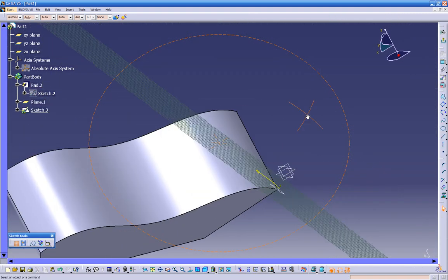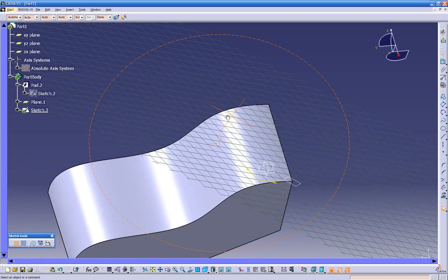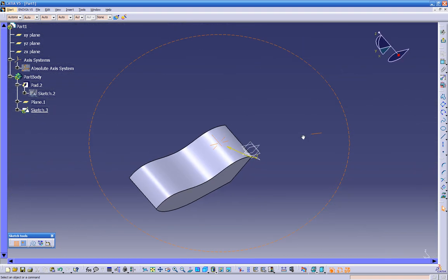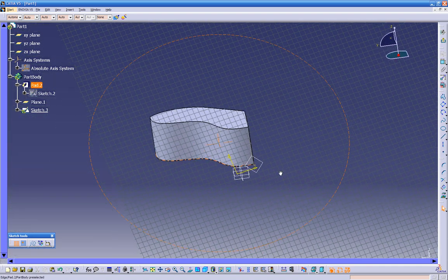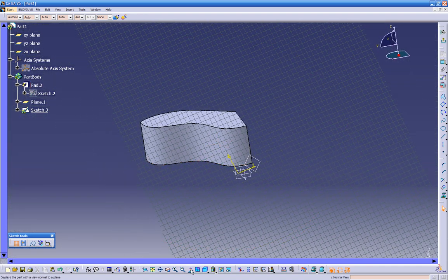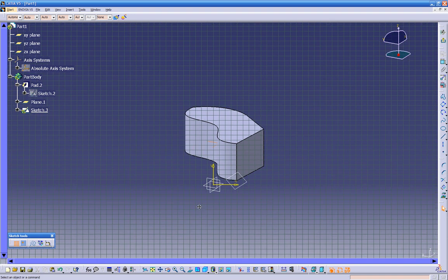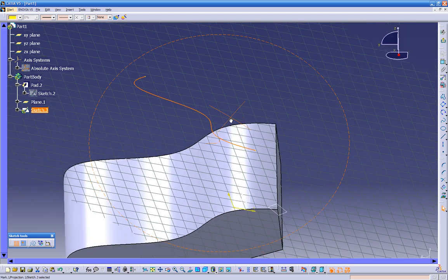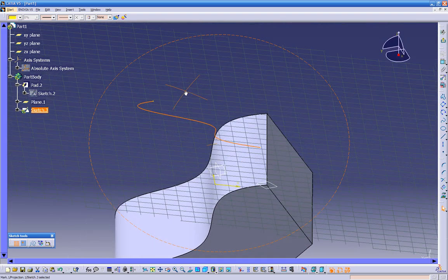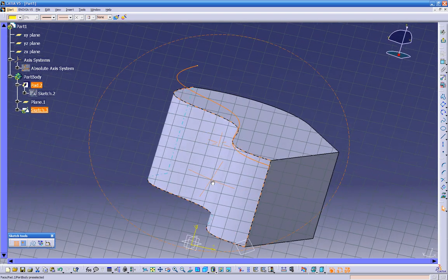So as you see right now, our screen is parallel with that plane that I just created. So let's click now normal to the view, and this is that option that I was just talking about. Click on it, and then click on the curve the way you like. And now watch this. If we rotate it, we can see our curve is projected into our view.